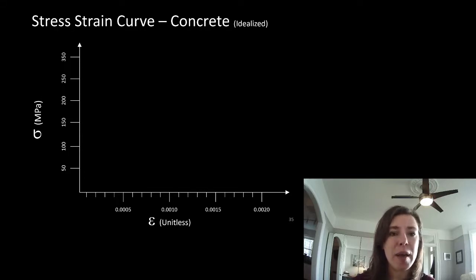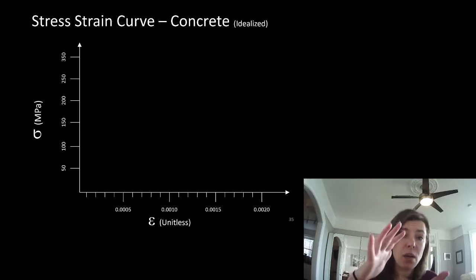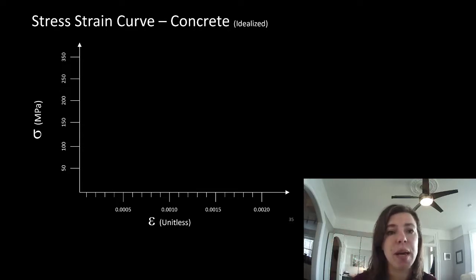It seems that way because we're used to associating so much of that stuff with ductile materials or something with a plastic zone. But concrete can take a load and revert back to its original shape. It's hard to notice, it's hard to measure because, again, these things are hard to notice on a large scale object. But that zone is there. There is an elastic zone in concrete.